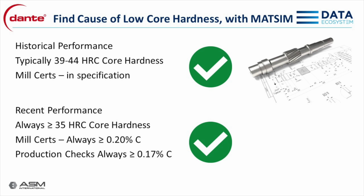Now you really know what's going on. This was a carbon problem. Your quench was in good shape, but a steel supplier switch by the service center unintentionally created a too low but in check tolerance carbon level, and that was enough to create the problem.